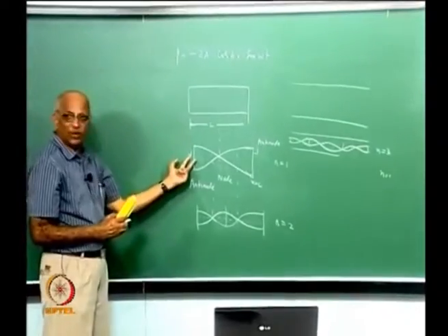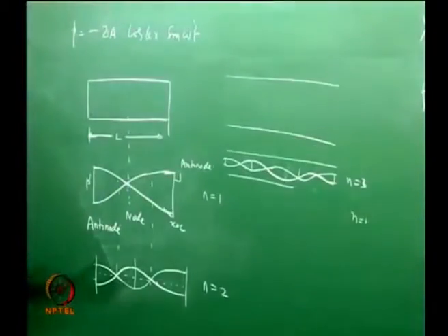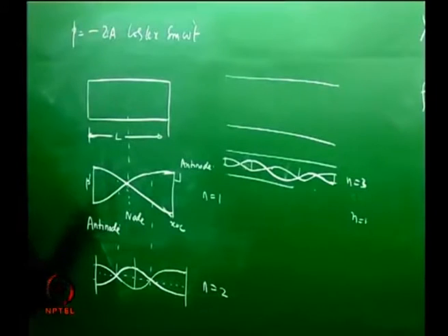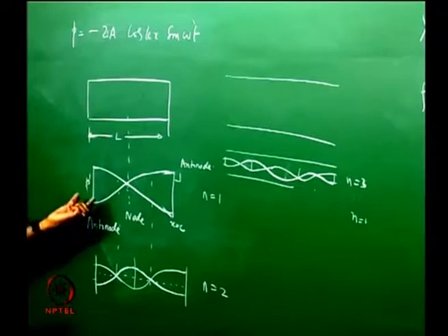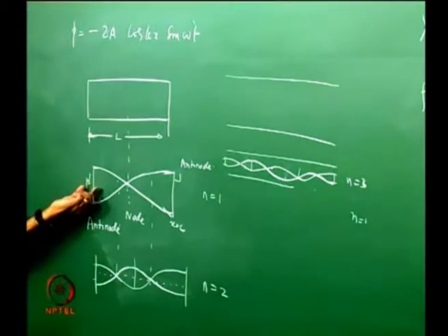It is also possible to get velocity oscillations. After all, in a chamber I am getting flow. I also told this is a closed end, therefore the velocity perturbation here is 0. How do I calculate the velocity perturbation from the pressure perturbation?